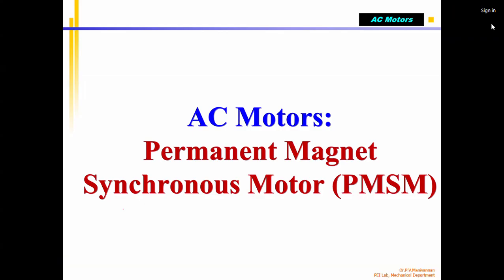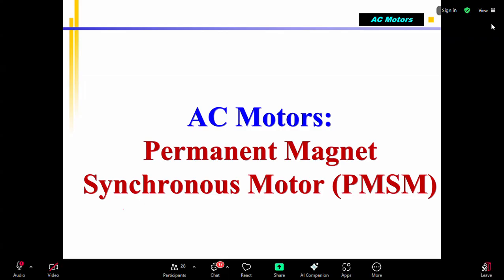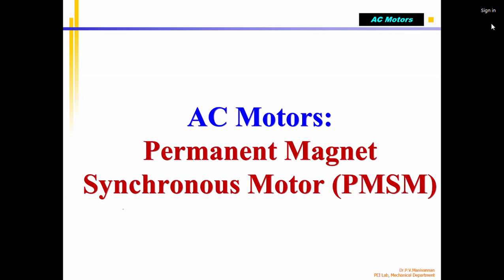Correct. So given the structure, if you vibrate the structure, the vibration happens because of rotation in the motor. That is due to motor speed. What speed? You have a motor which runs from say 0 RPM to say 5000 RPM. At a particular speed of the motor, it will start vibrating more. At that time the moving parts go into resonance. That is called mechanical resonance.